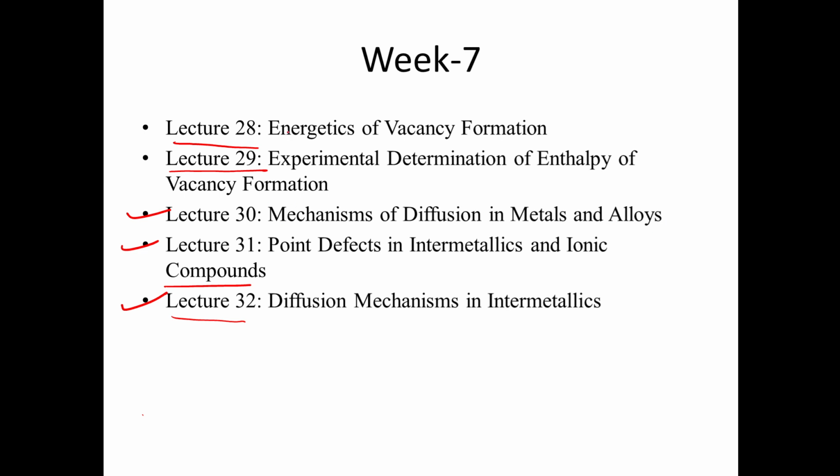In energetics of formation, how vacancies are formed: if a vacancy is formed in the innermost crystal, an atom is removed and placed onto a free surface, and how much energy is required to break the neighboring bonds, what is the enthalpy of formation, and whether the entropy increases or decreases by forming vacancies. Everything is discussed in lecture 28.